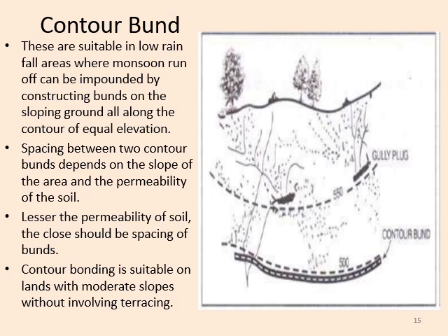Contour bunds are suitable in low rainfall areas, where monsoon runoff or rainfall water can be impounded by constructing bunds on the sloping ground all along the contour of equal elevation.